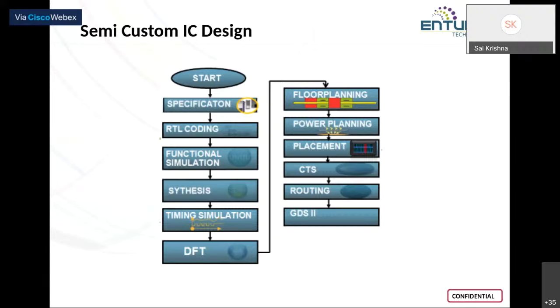But here we don't have any such real references. The functionality that you have built here is in the form of virtual logic, in the form of a high level program. So you cannot directly go on to physical design using that high level programming. So that is why, to bridge this gap between the functionality and the physical implementation, the PD, physical design, you take an extra step, synthesis.